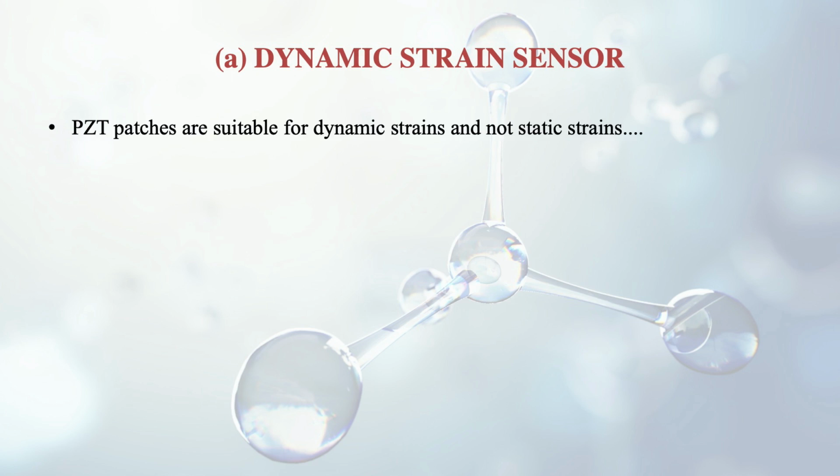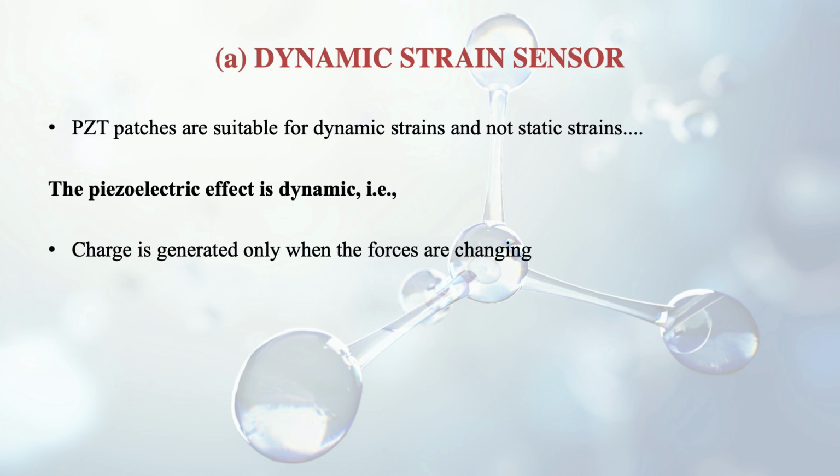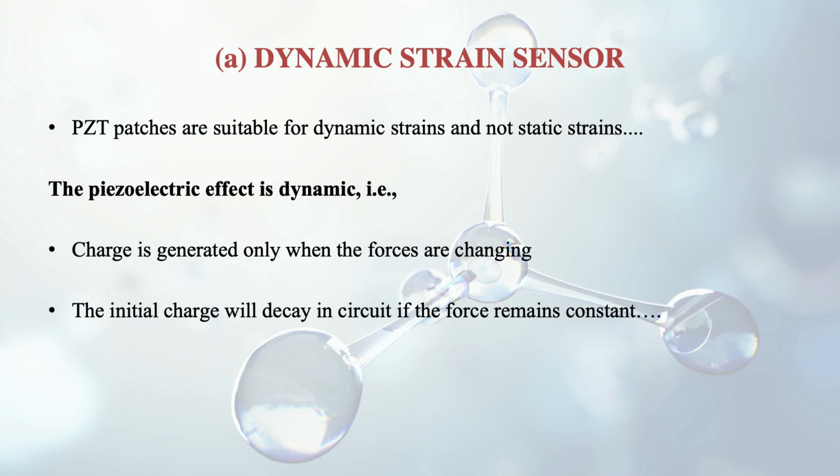It should be noted that the PZT patches are suitable for dynamic strains and they are not suitable for static strains. The reason is that the piezoelectric effect is dynamic in nature, that is the charges are generated when the forces are changing or the stresses are changing. If we have only a static force, then what will happen?